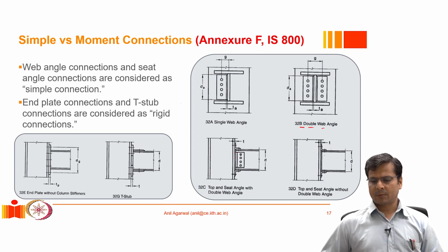These connectors that we are providing have very high stiffness against shear. So for example, this seat does not deform much before it starts resisting shear. However, when this system is subjected to moment, that is a rotation demand in the beam, you would observe that this angle can deform quite a bit in this direction.